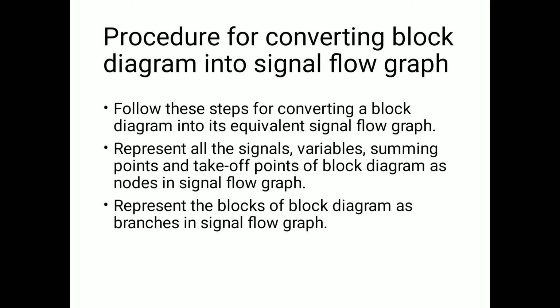The procedure for converting block diagram into signal flow graph. Follow the steps for converting a block diagram into its equivalent signal flow graph. Represent all the signal variables, summing points and takeoff points of block diagram as nodes in signal flow graph.